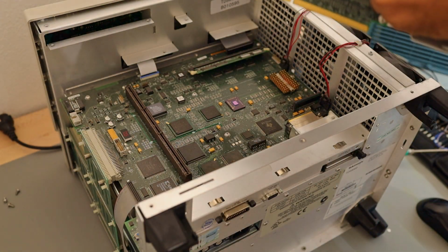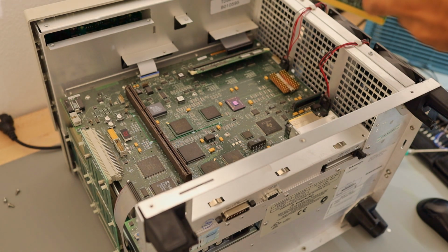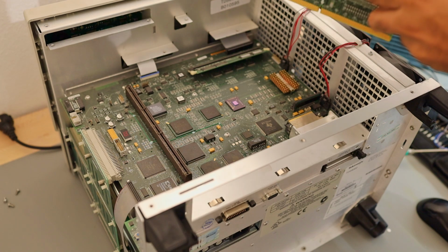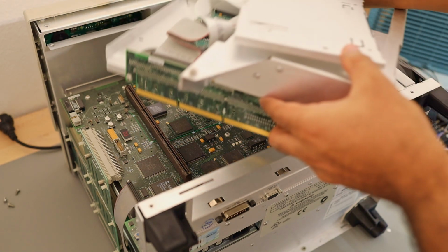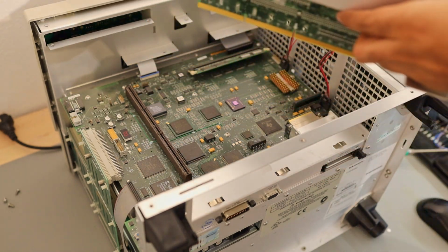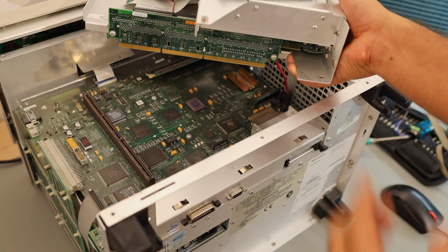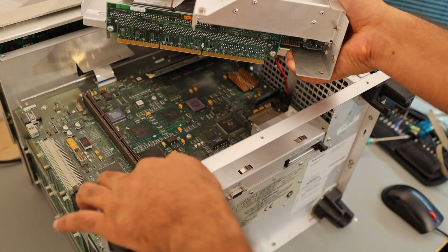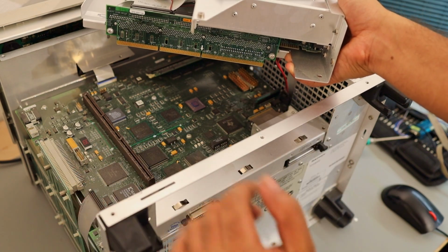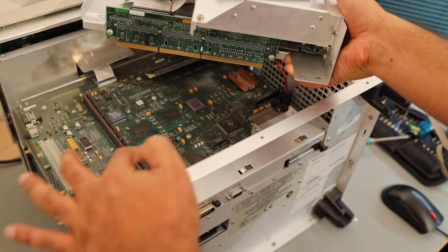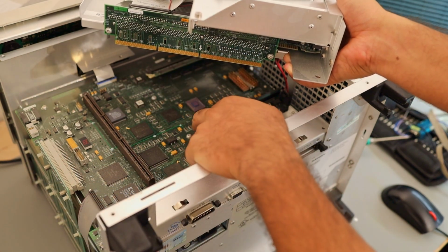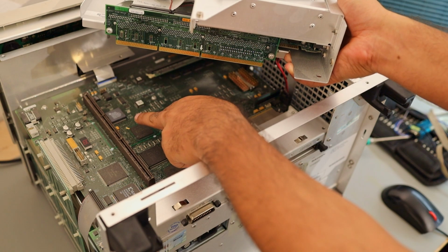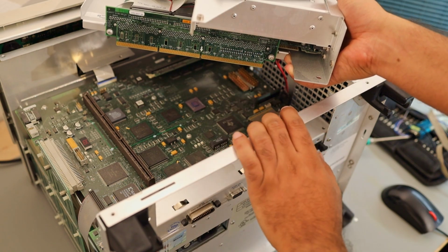So this connector, this goes to the VxWorks board, and that's where all the magic happens of the oscilloscope. Maybe I'll show you properly. This connector which you see goes to the VxWorks board. And this is the configuration memory which was covered by this motherboard, and there's a battery on top of the NVRAM memory. And we're supposed to check that battery as well.